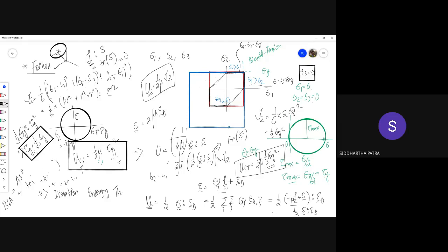Now if I look at the expression for J2 right there, substituting sigma 3 equals 0, J2 becomes this quantity. So the limit on J2: to be safe, J2 should be less than or equal to tau y squared. That's the criterion. Now the expression for J2, with sigma 3 equals 0, becomes 1 by 6.